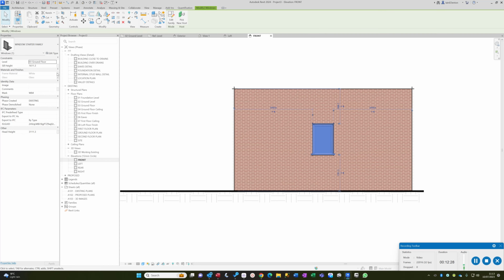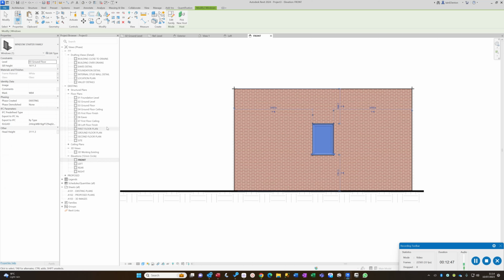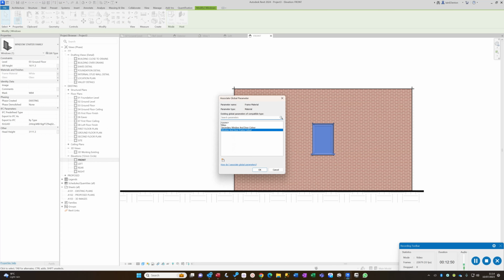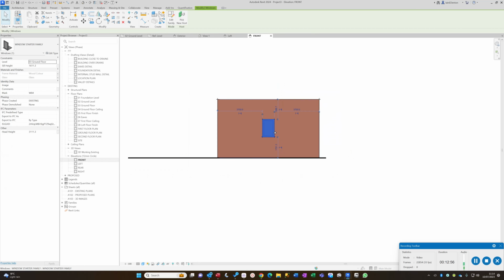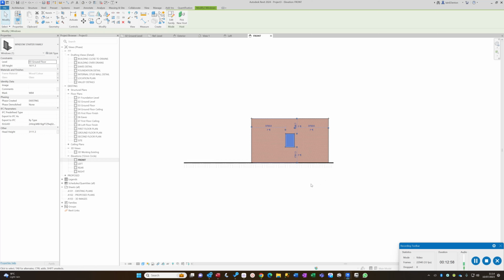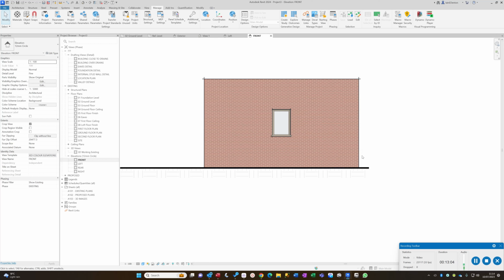And these here are set up by manage global parameters. So I've put window and door frame colour white. You create your parameter down here. Secondary window and door colour, wood colour, glass. If I click to this and then go to secondary window and door colour, that creates a brown one. I use that for windows and doors because it means that I don't have to go searching for particular frame styles, because they all tend to be the same time after time for each one. So I set them to the global one.